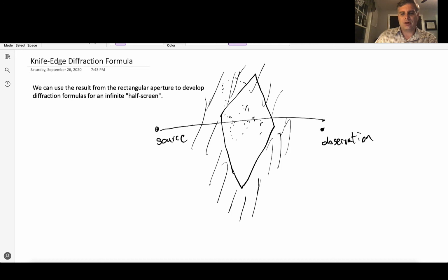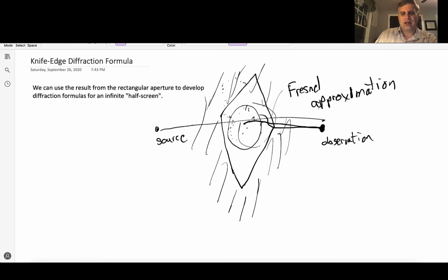And then we use the Kirchhoff-Helmholtz integral theorem to calculate what the field solution is at that point. We had a special way of solving it using the Fresnel approximation for phase, which lets you get much closer to this aperture than the far field approximation that we often use in antenna engineering and other problems. It's still an approximation, but it works pretty well.